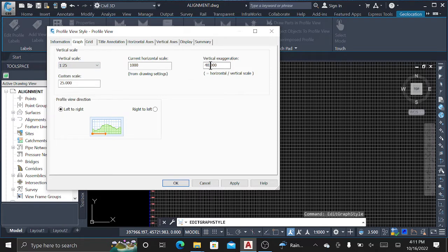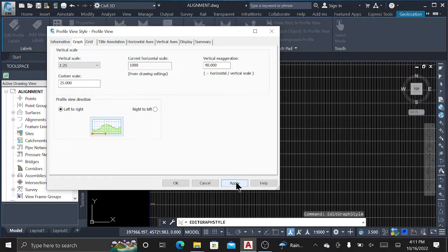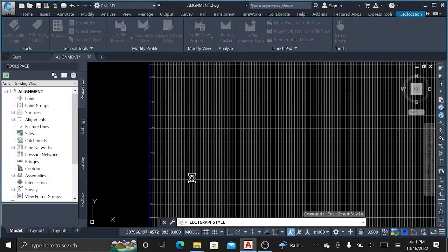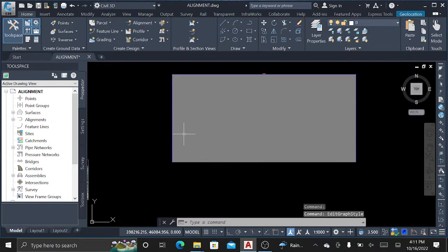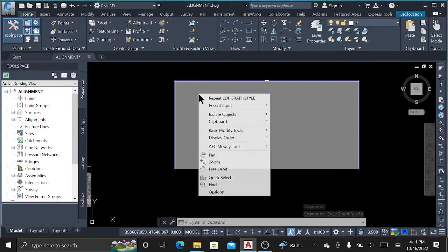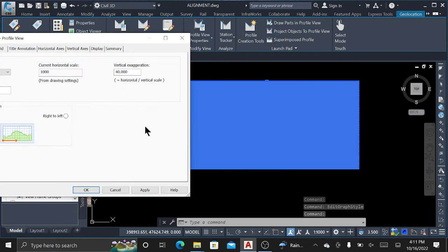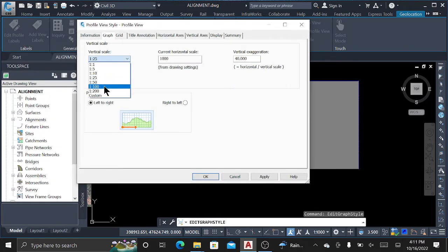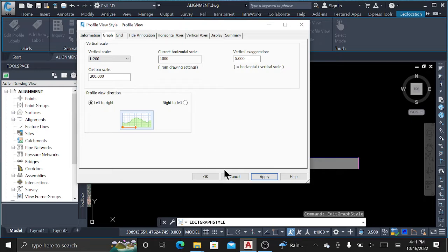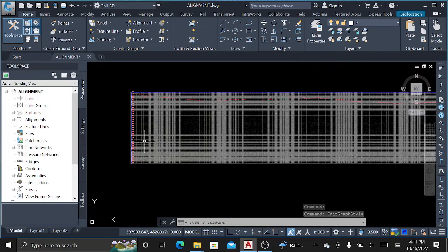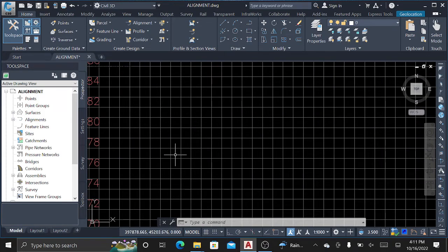Okay. So we'll be able to confirm for us, but we can try to use our guts and see which one is best representative of our graph here. So when I click on that, our graph has become taller, which is not really as representative. So I'm going to highlight the graph again, come to edit profile view. So I'm going to now just increase the rate, maybe 1 to 200, which makes our vertical exaggeration by 5%. Then allow for that. Now this is too short, I think, but probably could be a better representation. Now you have almost 1 to 1, same equal heights.